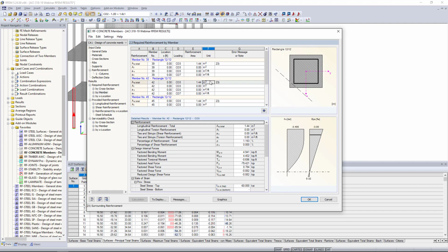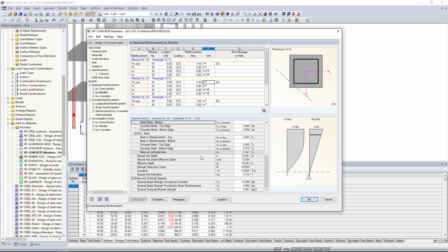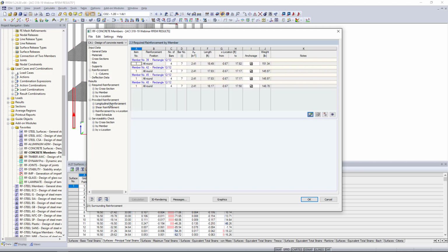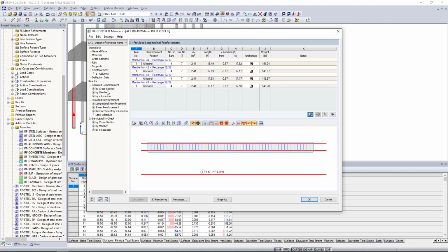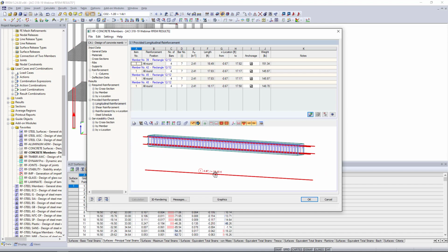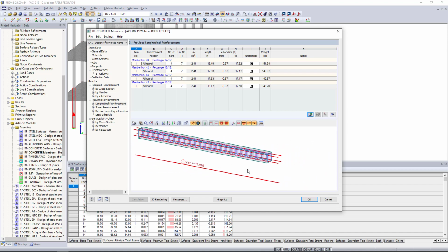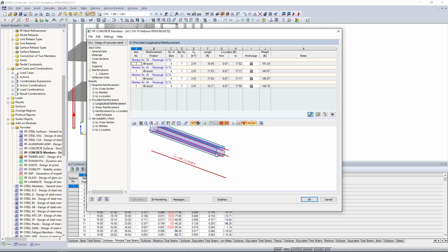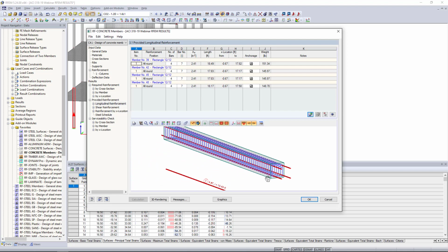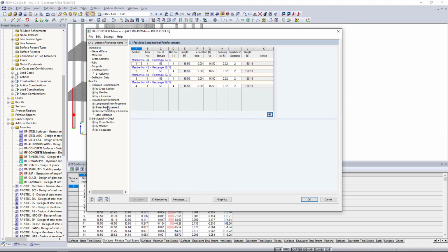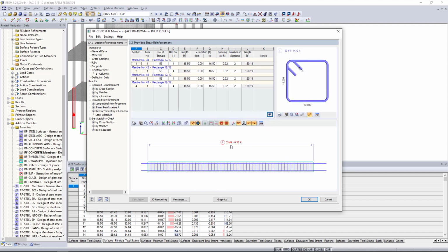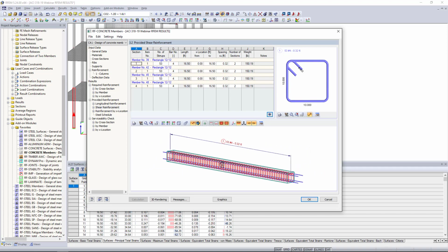Okay, so once we have this required reinforcement and the given variables are shown here, we'd like to know what the program's actually designing for this member, and that's under provided reinforcement. So for example, we can take a look at member number 39, and this is the longitudinal reinforcement. The program has come up with 4 number 7s located at the corners here. Same concept for the shear reinforcement. We take a look at the program has designed 53 number 4s at about 4 inches on center.